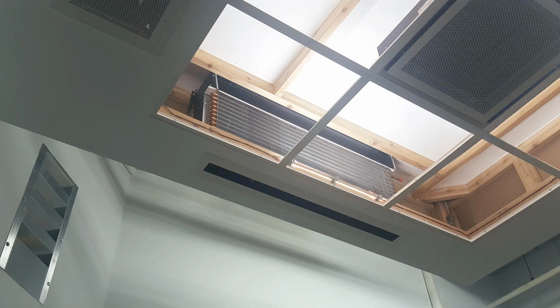And then you can essentially provide any sort of discharge slot or grill register connected to this unit, to suit the architectural needs in the space. It's just important to keep in mind, really staying above a 50% free area of the grill type, so that we achieve proper performance.